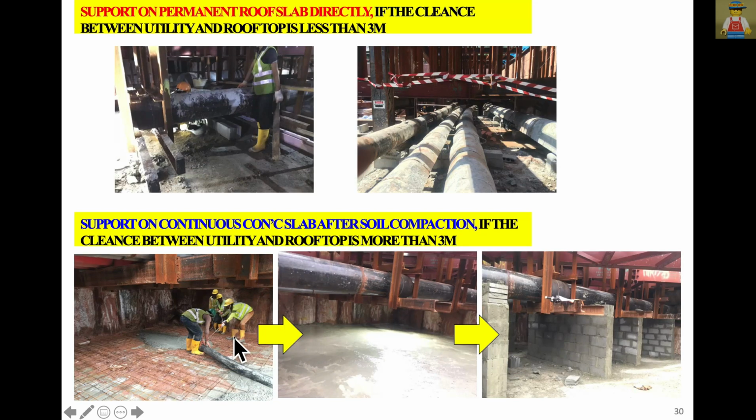After removal of angles, then backfill by LSS, which is a liquid type of cementitious soil, so that it can fill all of the gap below. So in the future, there is no settlement. But if there is no hard structure below, like just soil ground to come up, then cast some kind of concrete slab to support every 2 meters. So it won't settle in the future. After dismantling of all the angles, followed by LSS backfilling, then the remaining gap will be backfilled by sand.